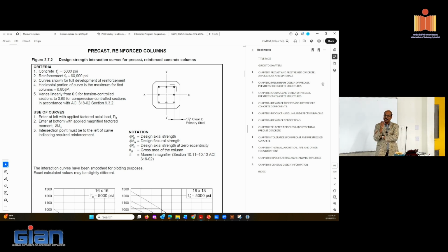So we do put some additional requirements on rocking structures. That's on top of this. It's not that they will not change the details. You could take this detail and say, I want this column, but I want confinement added to the bottom with the 135 hook. They will do it. But what they don't like is changing the dimension, because then you don't have the formwork, right?